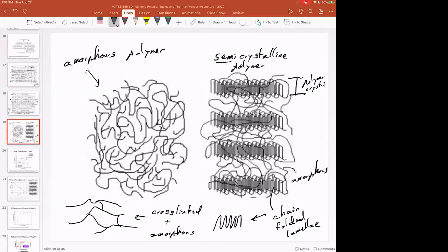Some polymers like polystyrene will never ever crystallize no matter what you do, no matter how long you wait. But because of the wonders of organic chemistry, if you make syndiotactic polystyrene or regioregular polystyrene, it is semicrystalline. And so that gets in the weeds of polymer science and how you design different polymers. So feel free to keep asking those questions. I'm not going to give you a lecture on stereochemistry in this class. I'm sure some of you don't want it.